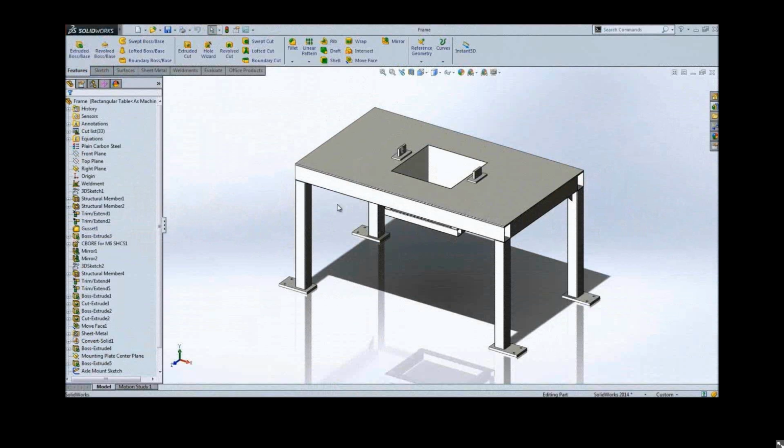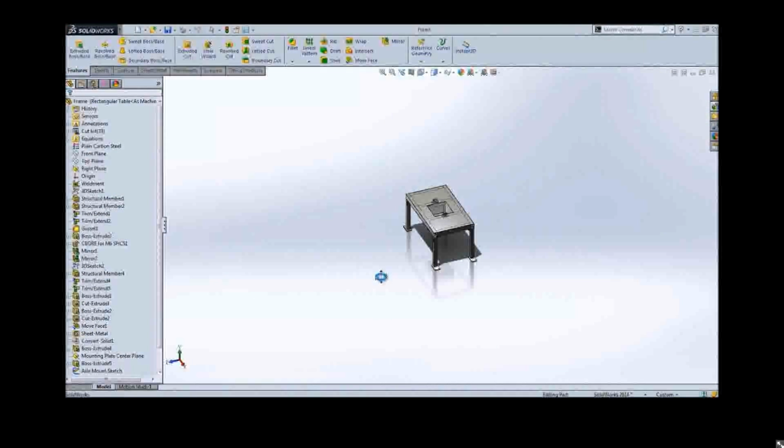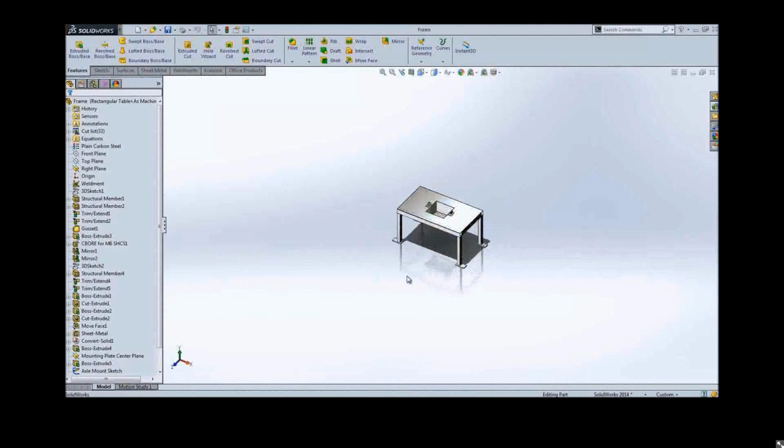All right, so as Eric mentioned, a lot of really good stuff in weldments and part design. The first, which I really like and noticed right away, is the edge bleed through for thin features. If you zoom out, and you probably noticed this in previous versions of SolidWorks, if you have a very thin part laying on top of another one, you'll get this bleed through, almost like sketching on top of the part. It's because the polygons of the very thin part get so small that it shows the polygons underneath it. They've taken care of that in 2014.